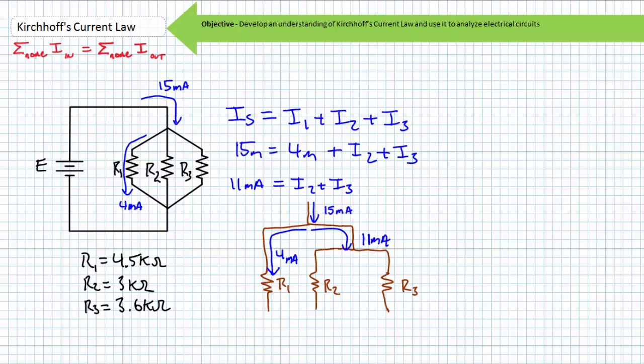Stop right here. Those individuals that know and understand the current divider rule shortcut can solve for the unknown currents in one step. You'll understand and appreciate this shortcut when we discuss it in a later lecture. Most importantly, the quick and easy KCL analysis got us directly to the point where we could apply the current divider rule shortcut using only basic addition and subtraction. We'll discuss the current divider rule in a later lecture. Remember this step though. KCL routes us directly to a shortcut.